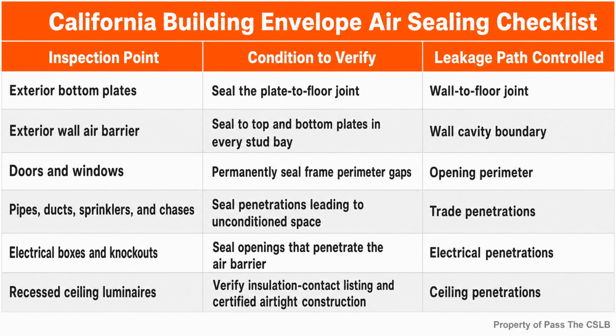Imagine a contractor who carefully verifies the bottom plate seal before rough plumbing. The plumber later drills through the top plate for vent piping into a ventilated attic. The pipe is smaller than the drilled hole, so an open ring remains around it. Nothing about the original bottom plate work closes that new path. The practical response is to identify and seal the penetration with a method appropriate for that location before insulation and drywall hide it.